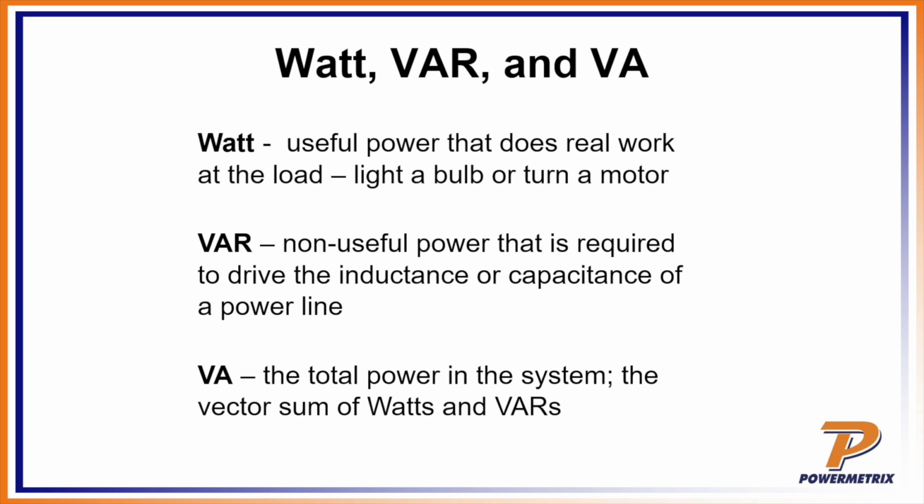It is real power. It does have to be generated, it does have to be transmitted, and eventually it has to be paid for. It's really just an artifact of the inductance and capacitance in the load. But as a utility, we would like to minimize the amount of VARs and maximize the amount of watts, because watts is typically what we're billing for.